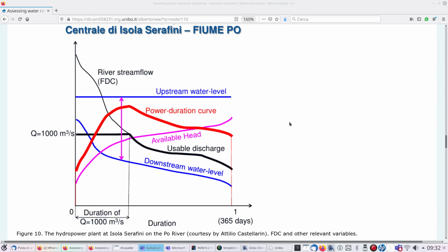Keep in mind that the flow duration curve is a classical question that I ask at the exam, and usually I ask the student to tell me about the two methods for estimation, what are advantages and disadvantages of each one. And as I said, the first method has a higher resolution, the second method allows estimation of uncertainty. This is basically what I'm asking. It's an important topic, and it's important in any design of water resource systems that are fed by surface water resources.